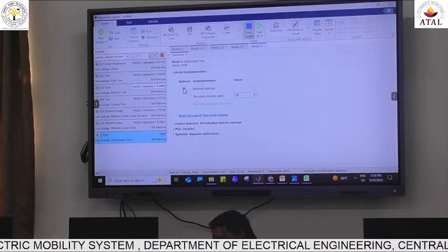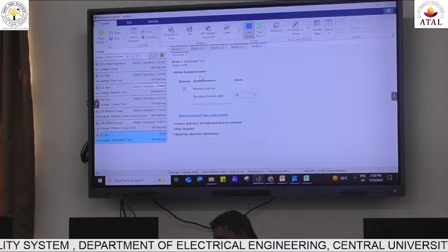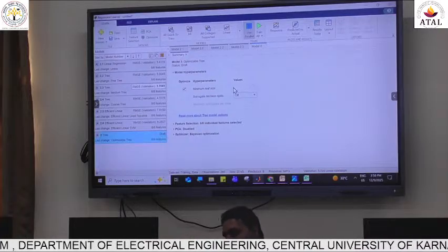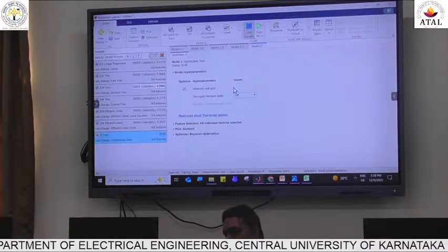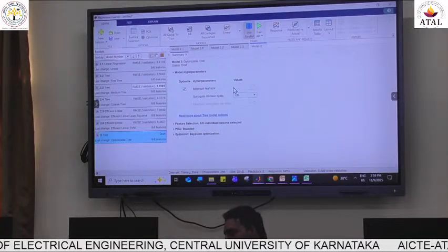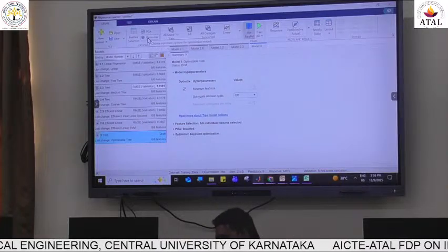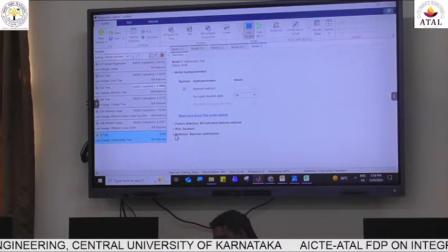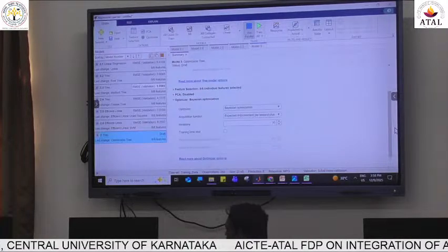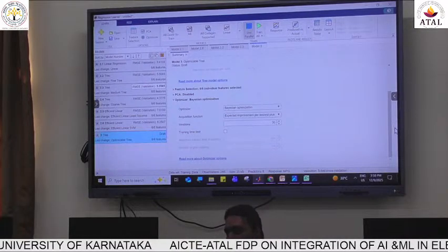But for this parameter, you can connect to the optimizer which we have here, and we can use our hyperparameter optimizer to optimize this parameter for reducing the error as much as possible. It will try to minimize the error as much as possible. So that is what your optimizer will do. Now either you can set up the optimizer options here, or you can set up the same optimizer options here also. Anywhere you access, you should get this interface, and you should be able to set up the optimizer options before we start the optimization.